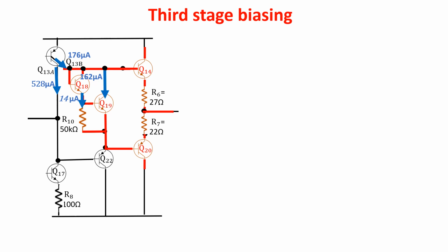The push-pull BJTs are large BJTs taking 4 times the area of Q19 to be able to provide enough current to the load. So we need to limit the standby current, which would be 4 times larger than that of Q19. That's why we properly underbias Q18, limiting its VBE voltage to 0.589 volts. The base voltage of the push-pull configuration is 1.24 volts, and if this voltage were shared just with the base emitter junctions of